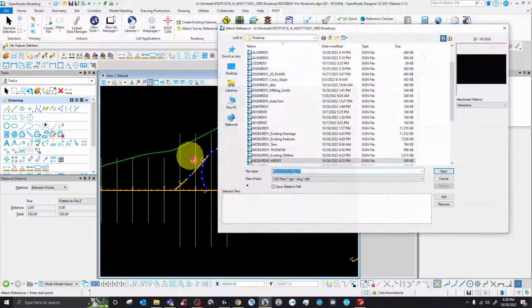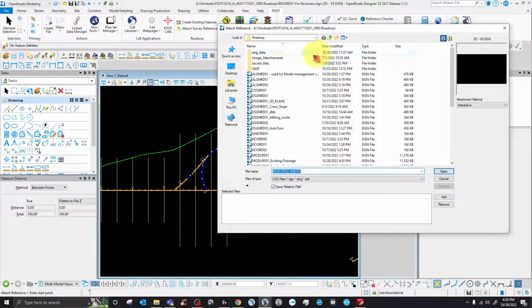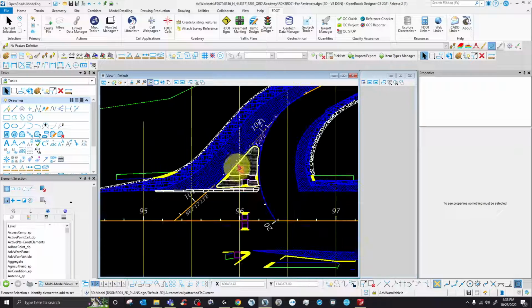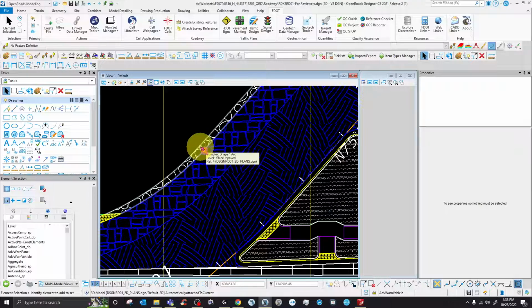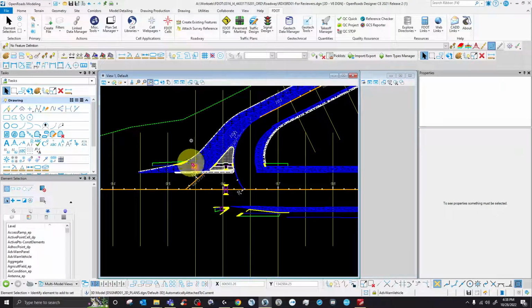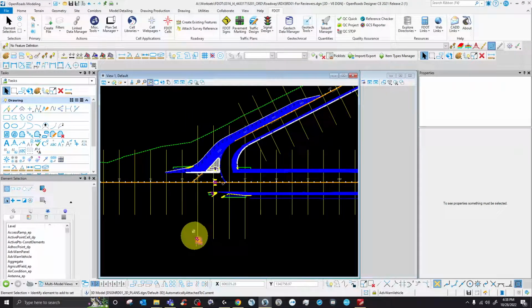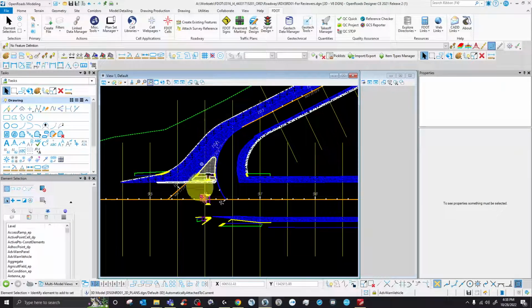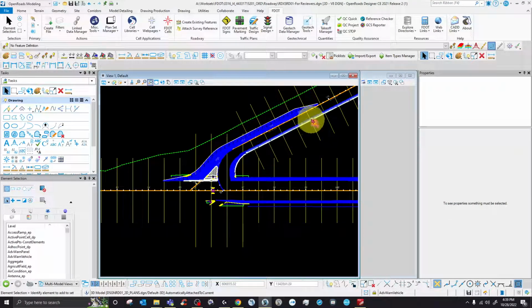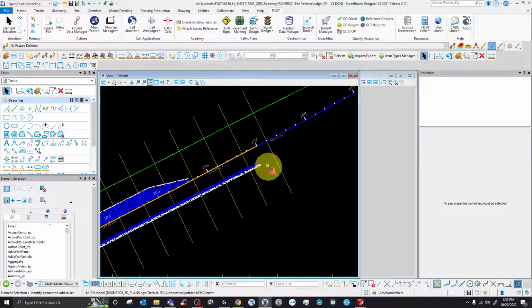Let me attach the proposed design so you guys can see what I mean. Just remember, this is the 2D. I'm just gonna attach the 2D so you can see what I mean. This is where we're widening the pavement, this is the widening of the paved shoulder, and this is the widening of the unpaved shoulder. Because I'm cutting the cross sections and we're gonna get to this weird area, I made these longer so they can show even this. Then I stopped here, and then I started from here, and again did 200 with an increment of 50 till here where we're gonna stop.